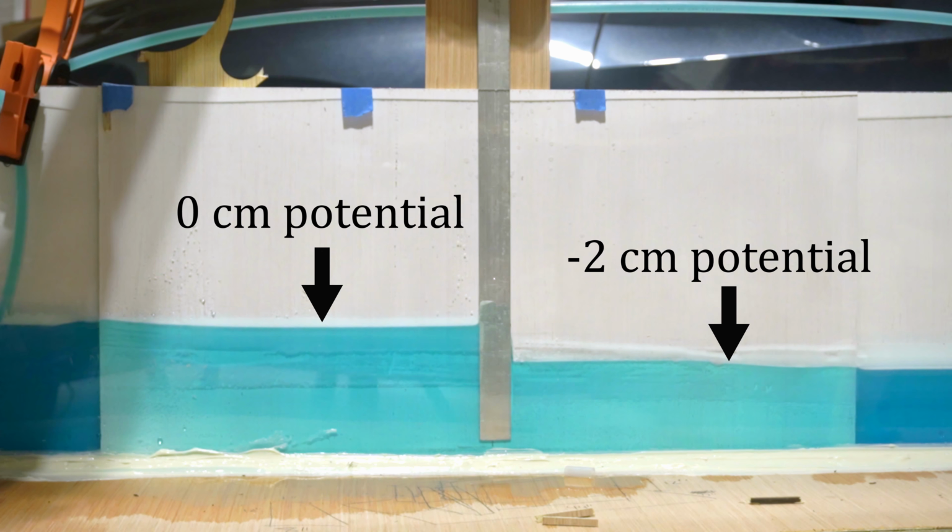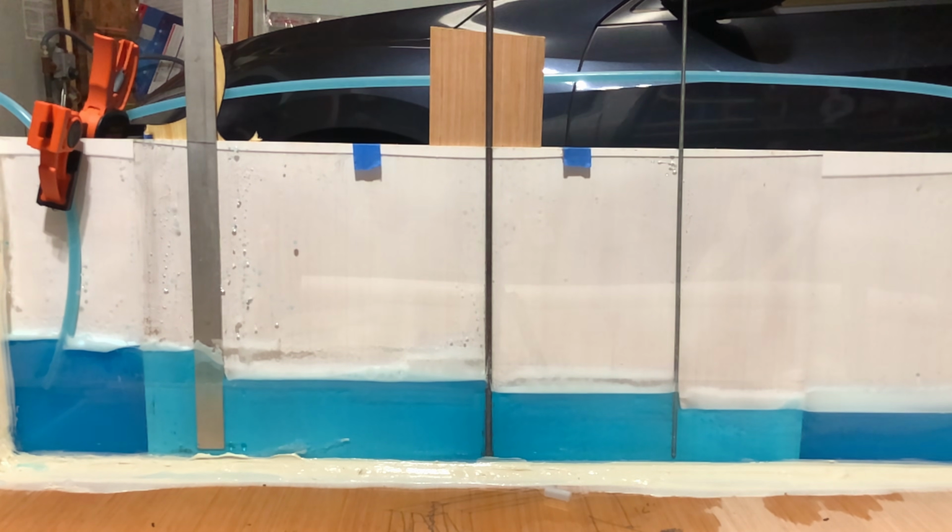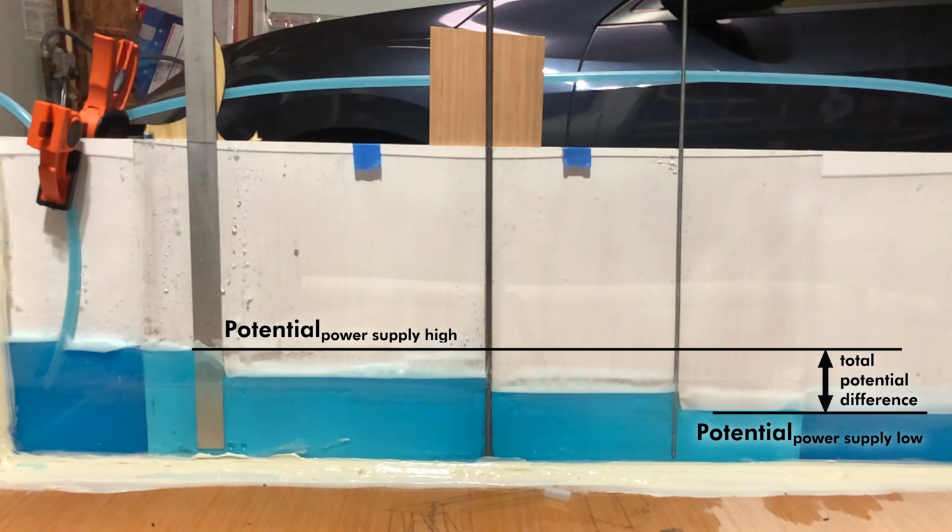When you want to look at the voltage drop across a certain component, you only need to look at the difference in potential on both sides of that component. As an example, when you put a bunch of resistors in series like this, it's called a resistive divider because it takes the total voltage drop across the entire circuit and divides it into chunks based on the relative strength of each resistor. If you tried to figure out what was going to happen in this situation using math, arithmetically with Ohm's law, what you'd end up calculating is the difference in potential, the difference in voltage on both sides of each of these resistors. In practice, this is normally known as the voltage drop across any given component.